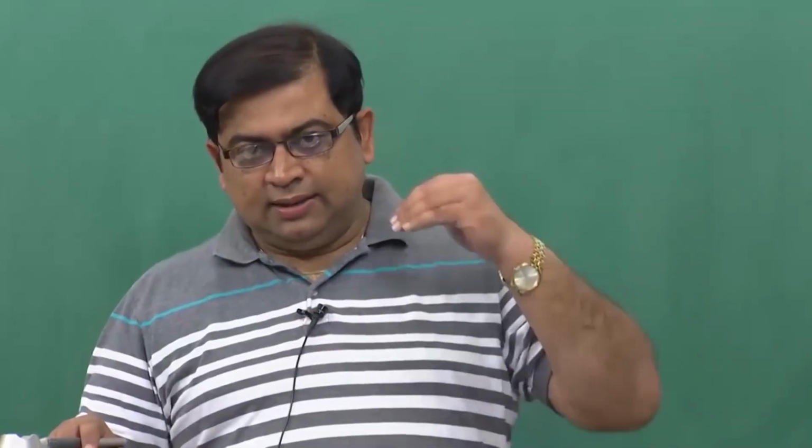If you are talking about the diameter of a shaft, what is the mean diameter of that 100 samples that you have recorded, and then an upper limit which would correspond to the maximum diameter which is recorded in these 100 samples, and a lower limit which is recorded as the minimum sample diameter which is recorded on those 100 samples. So this way you draw the UCL and the LCL.